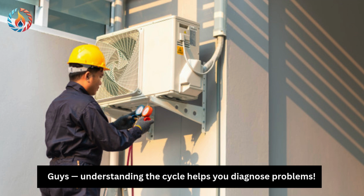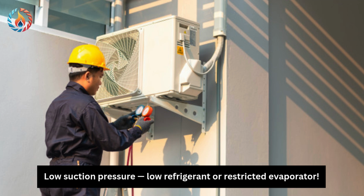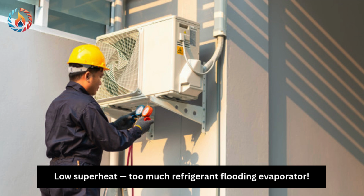Guys, understanding the cycle helps you diagnose problems. High discharge pressure, problem at condenser or overcharge. Low suction pressure, low refrigerant or restricted evaporator. Low superheat, too much refrigerant flooding evaporator.